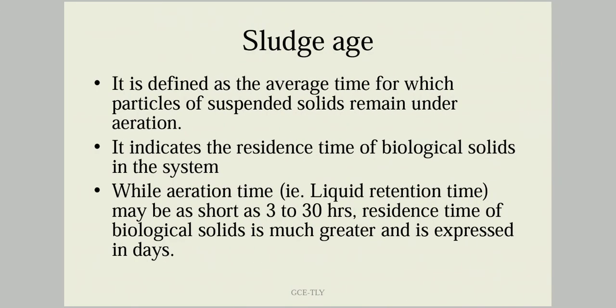Next is sludge age. It is defined as the average time for which particles or suspended solids remain under aeration. It represents the residence time of the biological solids in the system. It is different from the aeration time, that is the liquid retention time, which may be around 3 to 30 hours. The residence time of biological solids is much greater, and it is expected in days. So sludge age is represented in days, while liquid retention time is represented in hours.